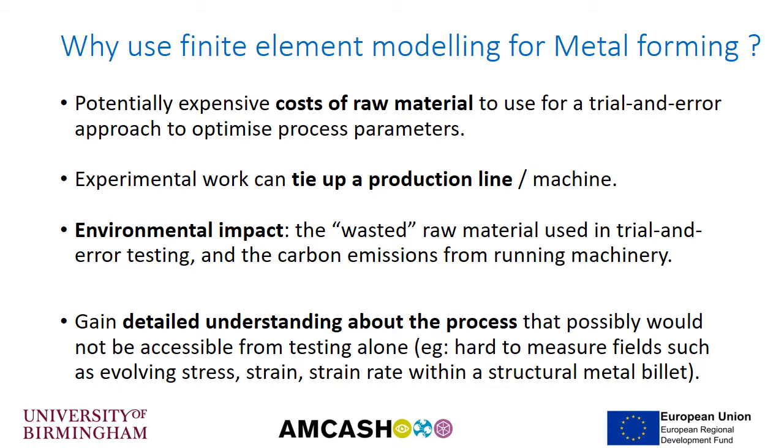There might be an environmental impact. There might be targets that you need to hit as a company, and we can help to reduce the wasted raw material and reduce the carbon emissions from running your machinery. And further, modelling can give a detailed understanding about the process, so we can understand more about what's happening inside the metallic billet that's being formed than would be achievable from standardised testing alone. So hard to measure fields such as the evolving stress, strain and strain rate within a structural metal billet can be visualised with finite element modelling.